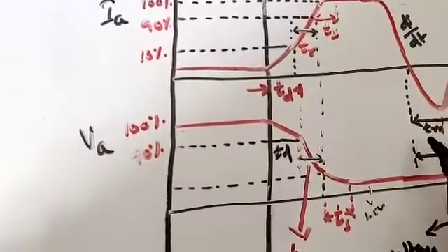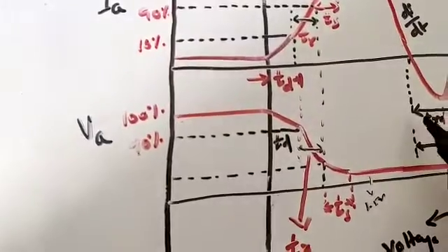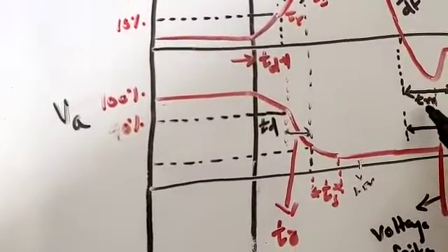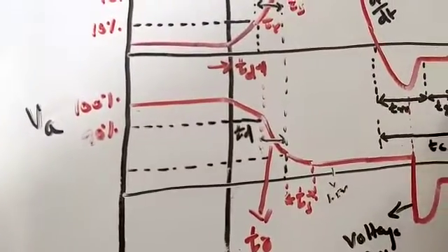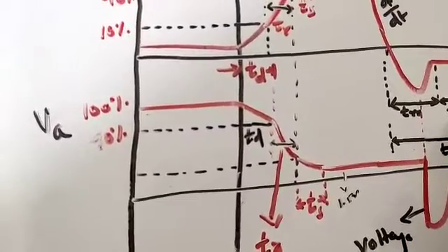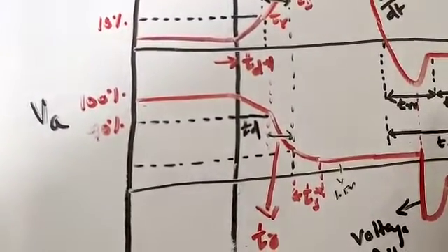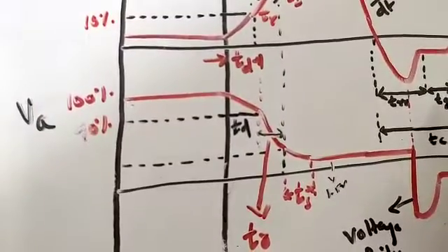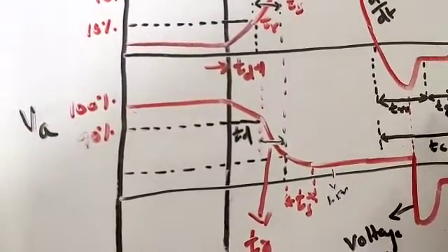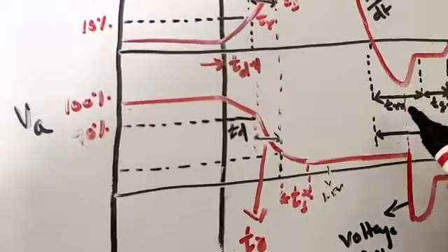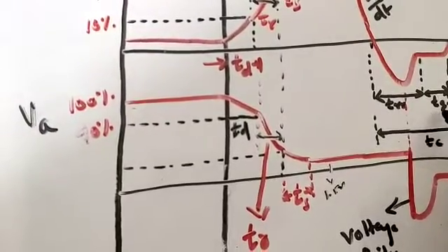the charge carriers from the junctions J1 and J3 is called reverse recovery time, TRR, and the time required to remove the charge carriers from junction J2 is called gate recovery time, TGR. So reverse recovery time and gate recovery time.